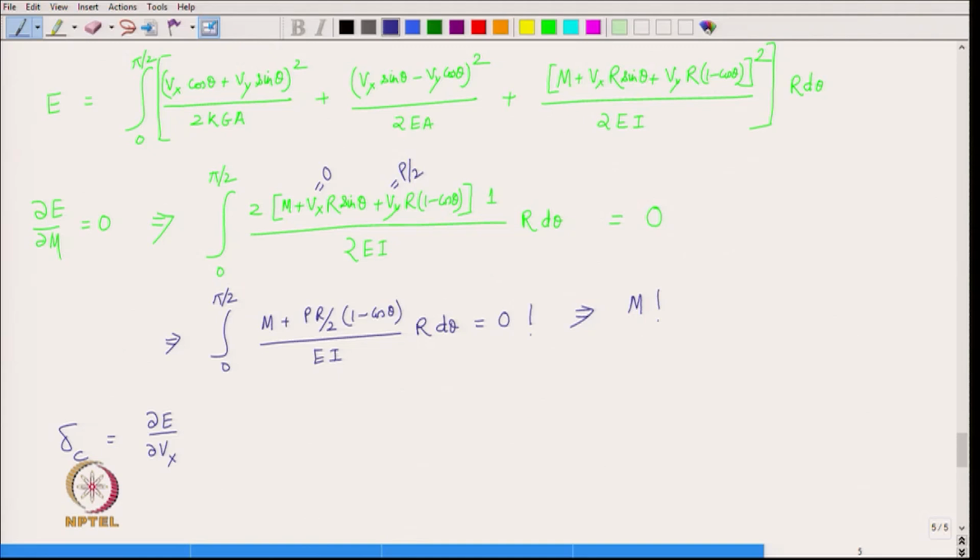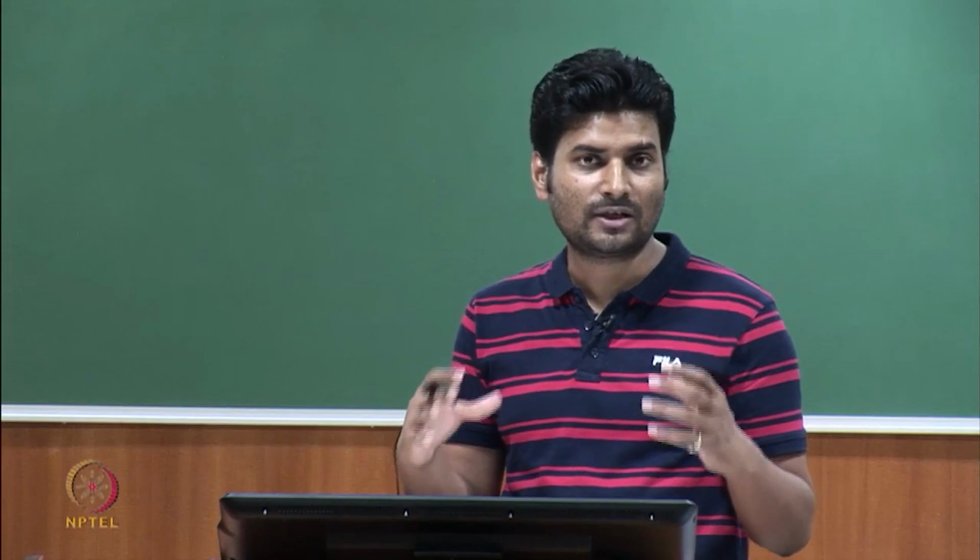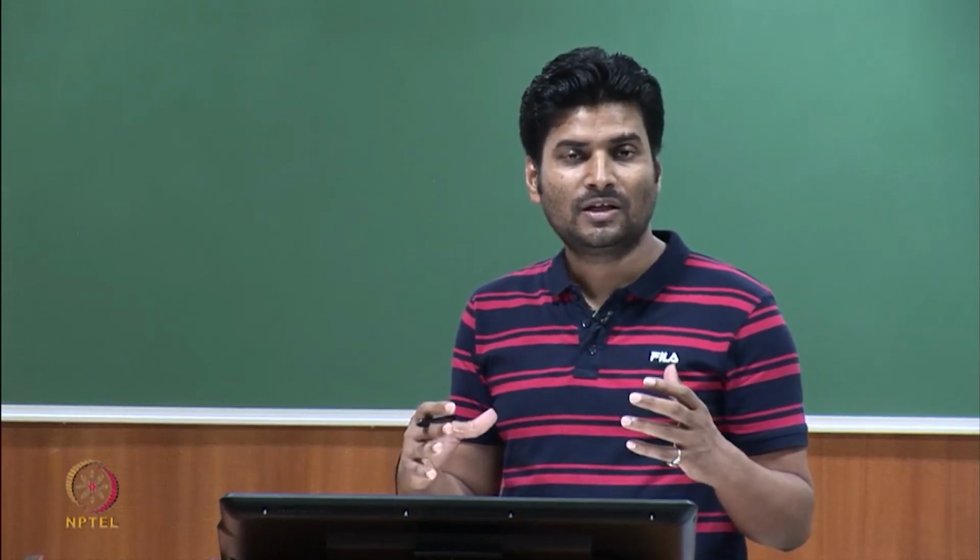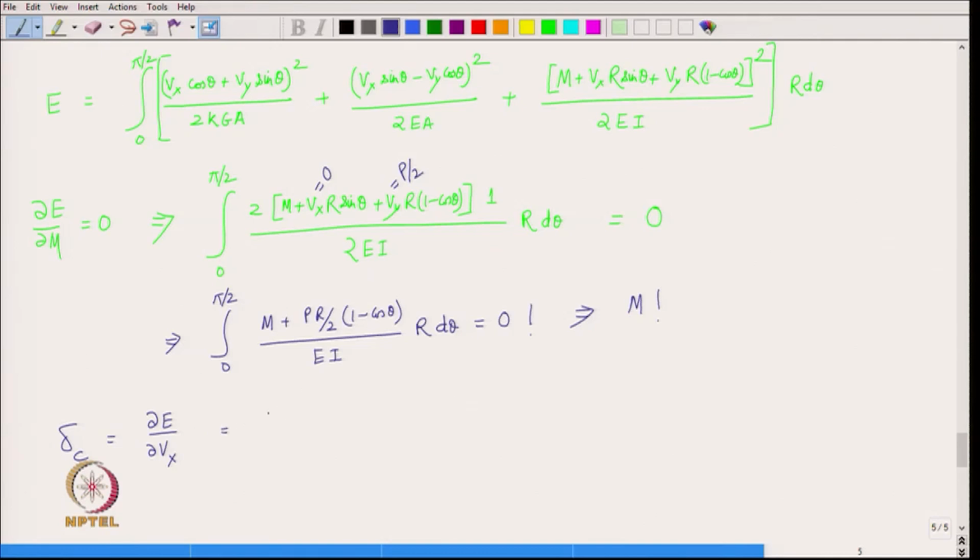Now, one approximation that we can do here is we can neglect the energy contribution due to shear force and axial force. And actually, whenever the beam is cylinder, whenever the length is large compared to diameter, or if the aspect ratio is really large, which is the case for beam, then bending energy and twisting energy, they are very significant, whereas the axial stretch energy and the shear energy due to transverse force, they are insignificant. Okay. So, we can drop the axial stretch energy and shear strain energy, all right. So, when we do it, we simply have to account the bending energy.